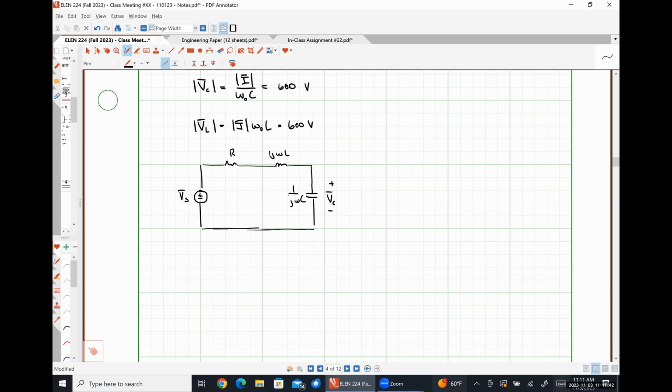That is not Q omega L, that is a shittily drawn J. Because we're just dealing with impedances. All right, so if I wanted to find the voltage drop across my capacitor in this circuit, I, being a lazy person, would just use voltage division because that would make it pretty simple, right? So using voltage division,